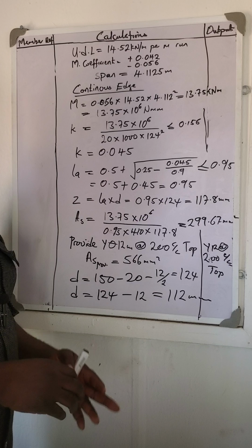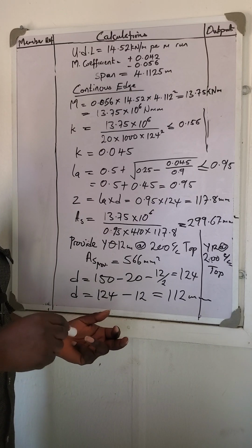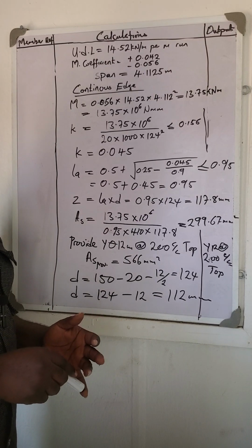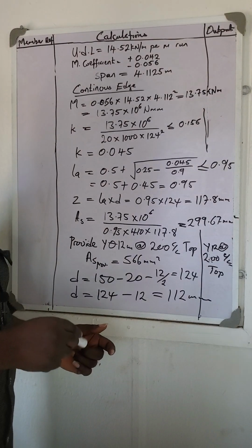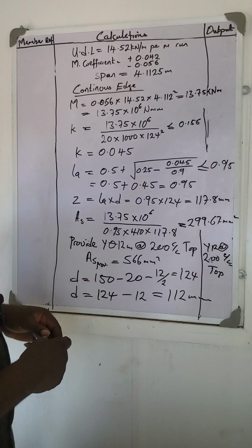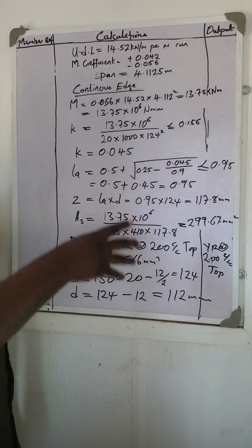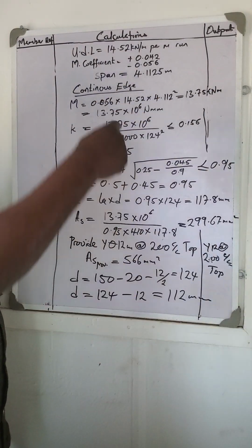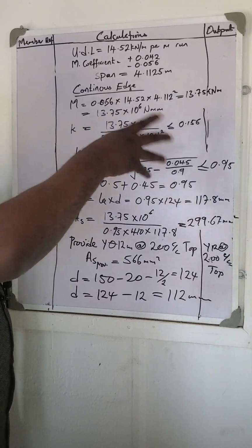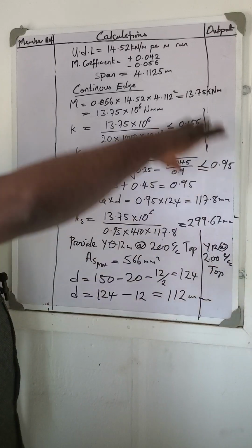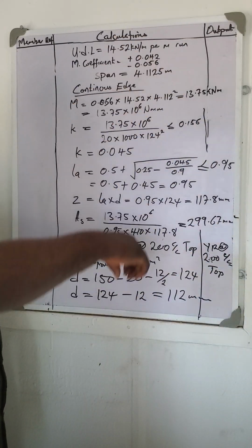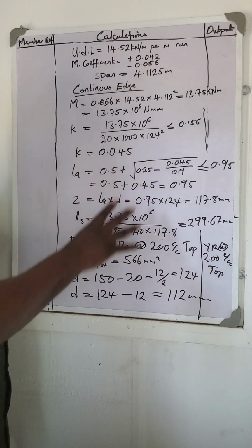What you need to do is get your information like the bearing capacity, your live load, your dead load. You include them there, then the span. You do your design in the software. After doing your design, all the parameters you need in structural design are there in the software. So that's what we are going to introduce this weekend.